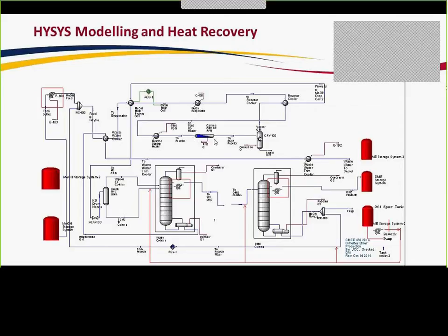After the reactor, we can achieve a 70% conversion on one pass, and the temperature rises to about 450 degrees Celsius. At this point, we have a mixture of dimethyl ether, a little bit of unreacted methanol, and water. Now we pass it through a couple of heat exchangers, one of them right here, and another one right here to remove excess heat from the stream.